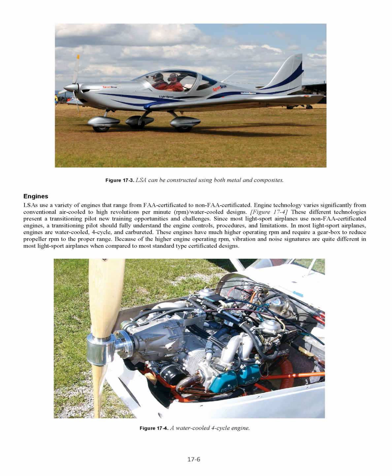Engines. LSAs use a variety of engines that range from FAA certificated to non-FAA certificated. Engine technology varies significantly from conventional air-cooled to high revolutions per minute, RPM, water-cooled designs. These different technologies present a transitioning pilot new training opportunities and challenges. Since most light sport airplanes use non-FAA certificated engines, a transitioning pilot should fully understand the engine controls, procedures, and limitations.